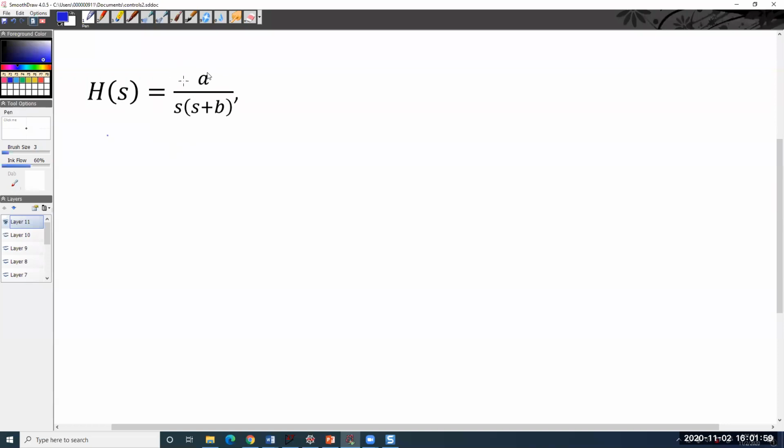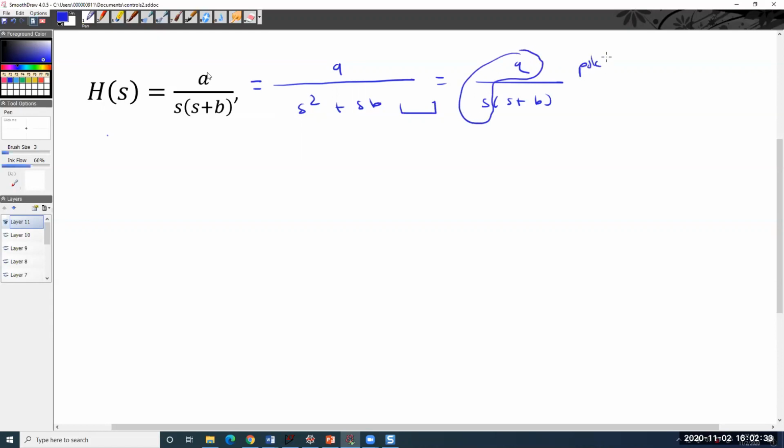So here it's easy to see that one of the poles is 0 and we'll have some kind of integrator function. But a lot of times you'll see this as s squared plus sb, and this is the missing term. So in order to get that it's at 0, well, you just convert it back. And now you can see that integrator type, pole at 0. All right. But when I'm fixing a problem, I like to leave it out like that.